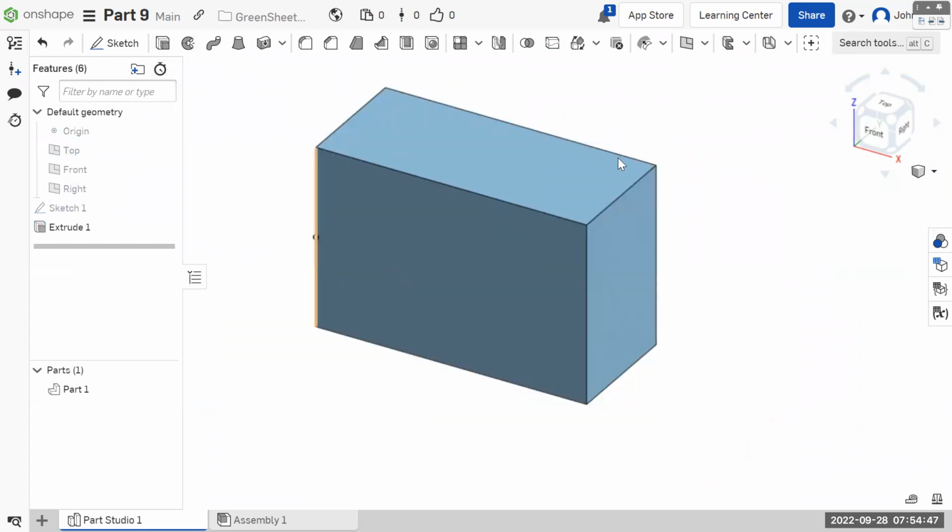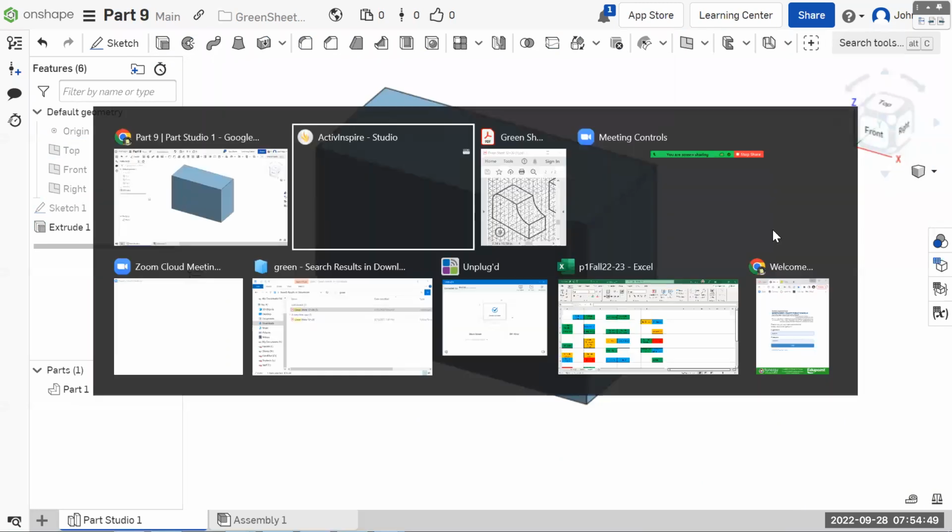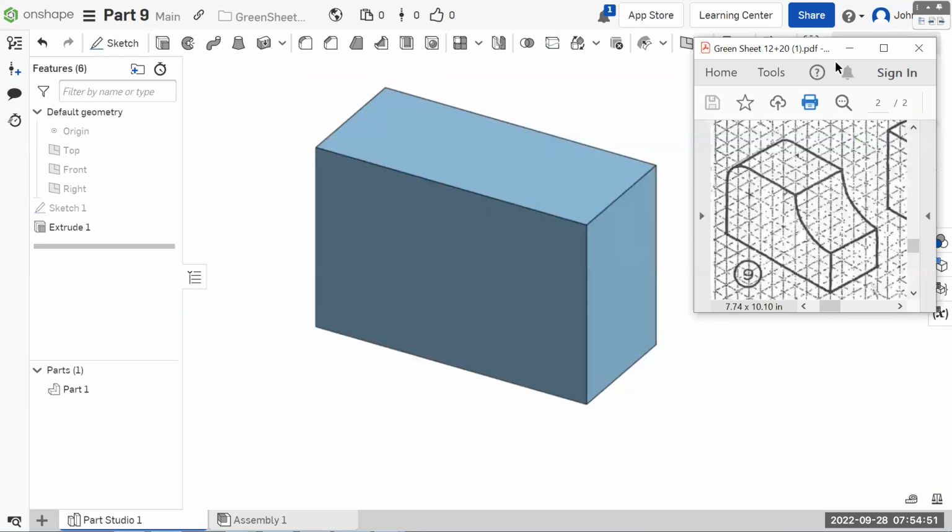We can turn off the origin point there. And we're going to do this in 2 other steps. First one, let's use the fillet tool, which is this one right here. You can see from the little pictograph what it's going to do. It's going to round over a corner, and we want to round over this corner. And the dimension that you put in is the radius of the curve, which in this case, the radius is 2,